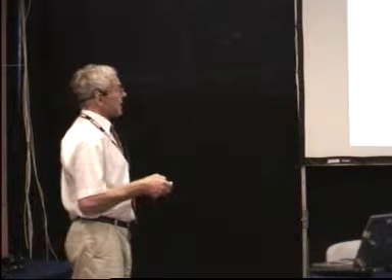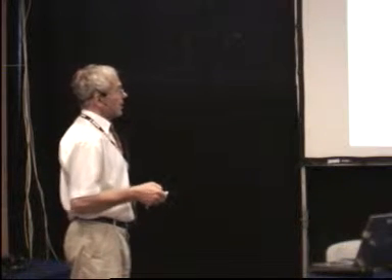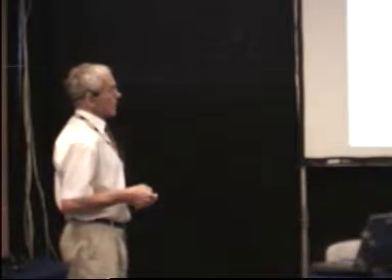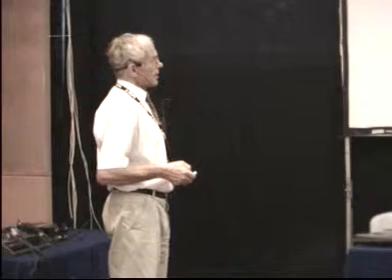These are the idlers in that case, and these are the newly generated signals. What you can see here are the second order signals, and here are the second order idlers. Unfortunately, the level of these second order idlers and second order signals is so low that they cannot be used for multi-wavelength conversion or multicasting purposes.